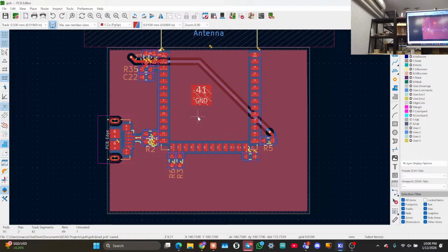Exactly. Yeah, so we have 4 layers: power layer, ground layer, wiring layer, and backlight. Yes, that's quite a common structure. Actually, we'll go through better examples of what a good PCB is. Usually it's much more beneficial to do signal, ground, signal, and then power is just ground. And this is for funny reasons. They're actually shorted together. They're still the same ground.